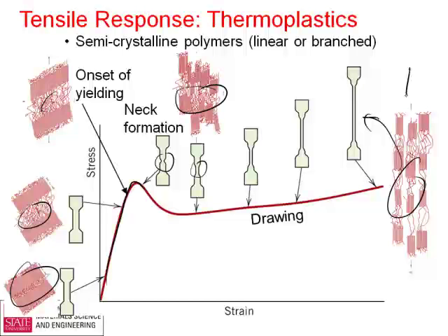As a result of that, you see extremely high stiffness and extremely high strength along the tensile direction of that polymer. This is also a fairly low entropy situation where everything is stretched the same way.